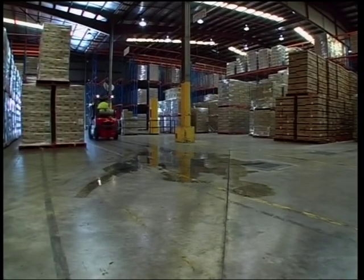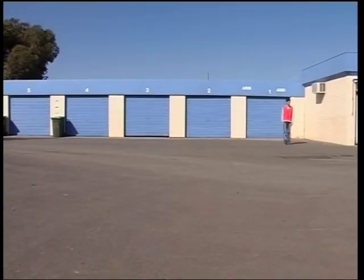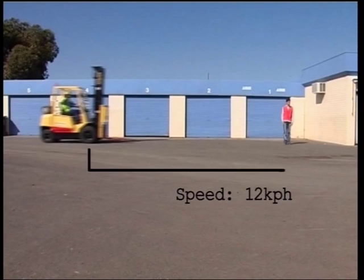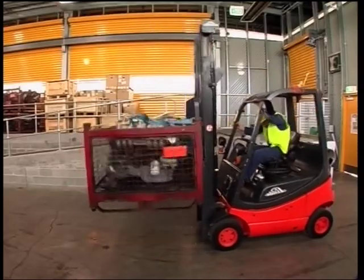Stopping a forklift is not the same as stopping a car. A forklift has only two small braking wheels. Keep in mind, studies have shown that if you are traveling at 12 kilometers per hour, it will take you 7 to 8 meters to come to a complete halt in an emergency situation. If you brake too quickly, the result is dynamic instability and a tip over.